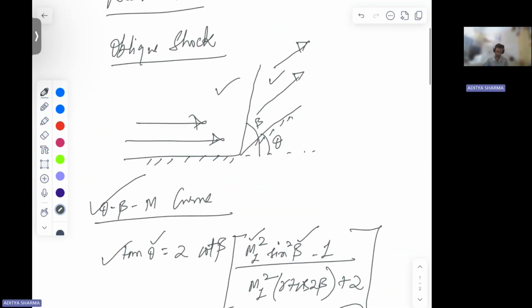So now if you see this, this basically means that if you are going to increase the Mach number, let's say we have some Mach 2, then we are increasing it to Mach 3. So this deflection angle for which we are going to get an oblique shock, for which your flow is going to remain attached, for which you are not going to get any bow shock, this deflection angle you can increase.